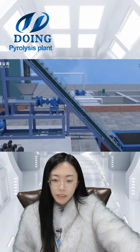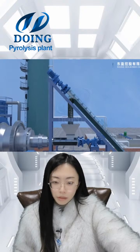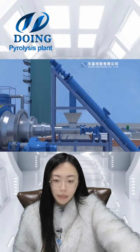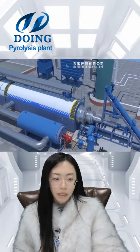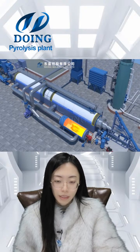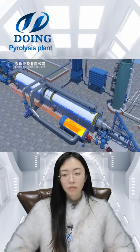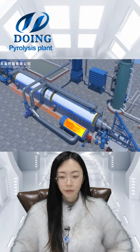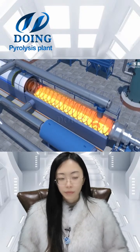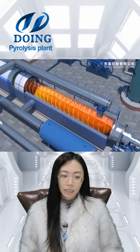The first is the feeding system, where we need to feed the rubber powder and do some pre-processing to crush the waste tire. Or if your material is household waste with some plastic inside, we need to use the plastic crusher to crush it into particles. The second is the pyrolysis system for heating. We use indirect heating, using the hot wind burner to heat the reactor.